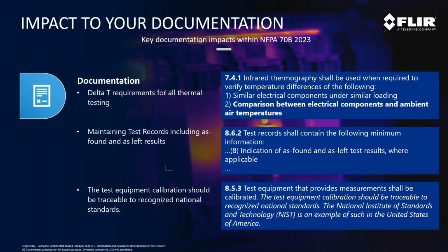And then the last one within the documentation side is test equipment calibration should be traceable to recognized national standards. We hear the term in the space all the time called NIST, so the National Institute of Standards and Technology. That is a recognized national standard, and the equipment itself that provides any sort of measurements. So this is not just thermal cameras, it's any sort of test and measurement tool you're using in your electrical inspection program needs to be calibrated, and the calibration should be traceable. So it's important that you ensure that the tools that you're using to perform all these tests are calibrated and done so against the national standard that's out there.